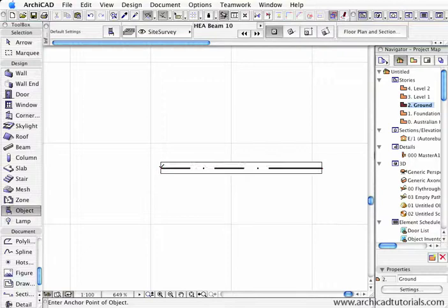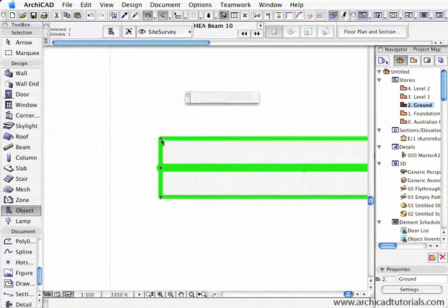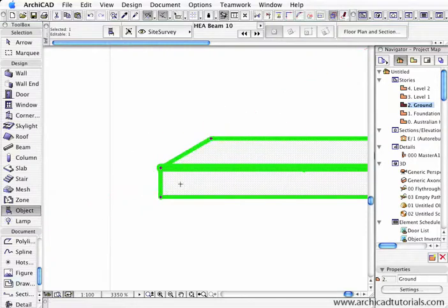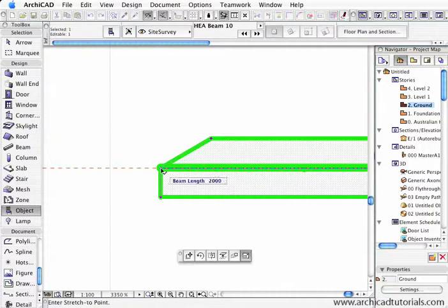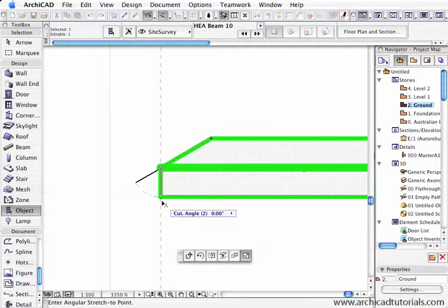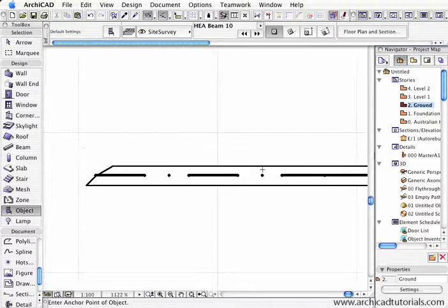and we can grab any of these by the hotspots, and we can type in the angle in the tracker palette once again, but I can use the guides. For example, if I wanted to cut that at a 60-degree pitch, if I select this hotspot and I wanted to maybe make that at minus 45 degrees. So we've got a very flexible tool with the beams now, and on top of that,